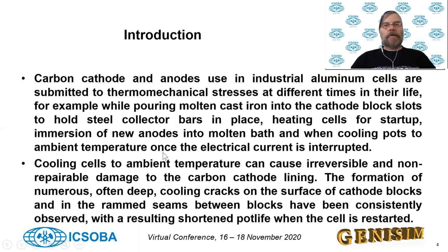The introduction is that there are many ways to damage cathode blocks and anodes by thermal shocks. One thermal shock we try to avoid is during the preheating of the pot, and when you put the new anode in the bath, you have some stress there. And then when you lose the power on the pot line for some time, and the pot is cooling down,